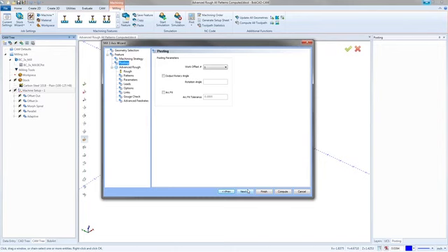That's the worst thing. A lot of guys get nervous. You sit here computing a toolpath. I had a toolpath the other day that took about 30 minutes to calculate. It was a real fine toolpath, real good finish getting put on it. And I didn't want to wait 30 minutes every single time I wanted to make a small change. And that was one of the small changes I had to make, but you don't have to recompute. So just remember that. I'm going to go ahead and turn it on and then hit next. Real quick, the arc fit tolerance is set to 0.5 thou. That's a pretty good place to be.